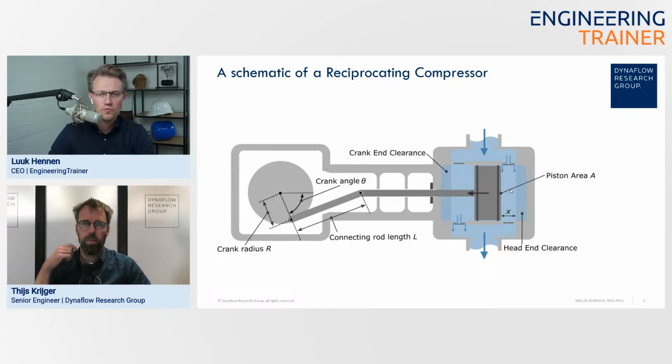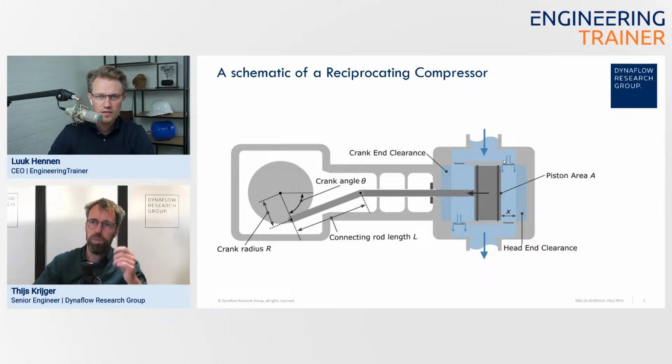You mentioned various times the word compressor and the word gas. Does this also hold up for liquids? So for liquids, the same principle applies. For reciprocating pumps, we will call them rather than compressors. But the same basic principle holds true, in that you also have these check valves and this piston moving back and forth to compress a volume up to a certain pressure, and then expansion when it moves back.